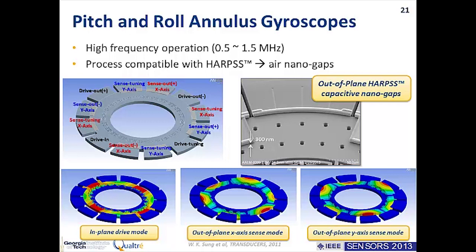So if we go to lower frequencies, obviously you're going to get higher sensitivity. But at lower frequencies, you might not get the same amount of speed. So these two factors might cancel each other. So what we get for our devices is very similar levels of scale factors. And then with the electronics, you can just compensate for any difference to get about the same output range.